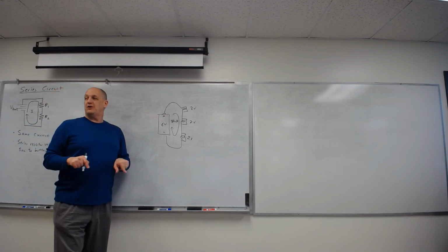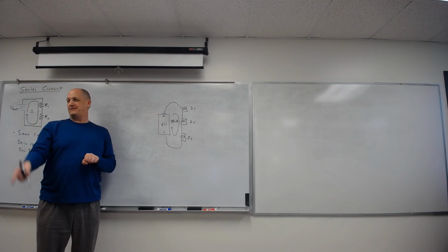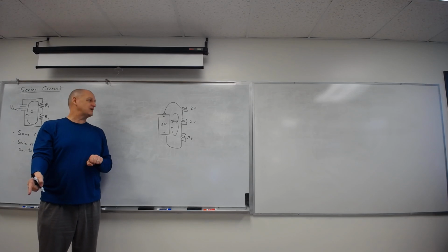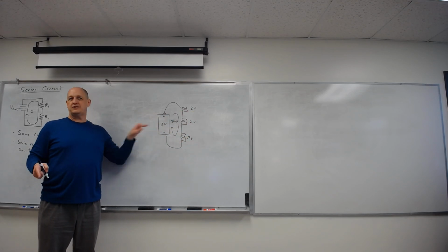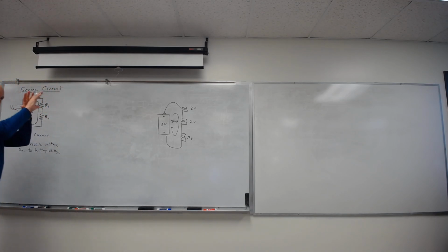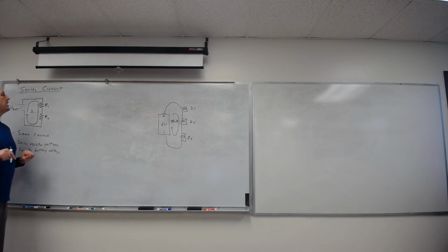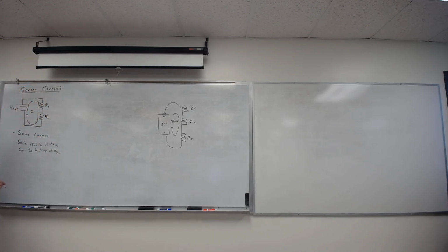When I looked at the table, I look and go, all the currents ought to be the same. They all ought to be labeled milliamps. If they don't have milliamps, I don't care what your numbers are. And the 3 voltages on the bulbs should add to the voltage of the battery. So, in theory, identical values. When you measure it in the lab, you might have something off in the end, which is a little bit of change. Okay, parallel. Well, let's do this because we've done power.